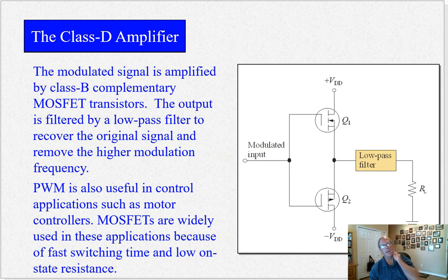All right. The other good thing about controlling a motor with pulse width modulation is that the torque of the electric motor is preserved with speed, because the motor is basically being turned on all the way for a short period of time at lower speeds, as opposed to just being turned on a little bit with a lower voltage, and therefore you don't get the full torque. But you can by turning it on all the way, if you understand that. The other thing about MOSFETs used in these switching circuits is they have low on-state resistance, which improves the efficiency. Okay, so they don't get hot.